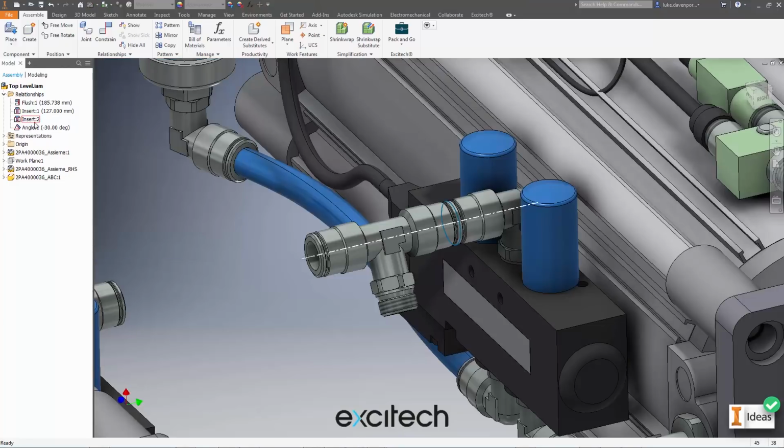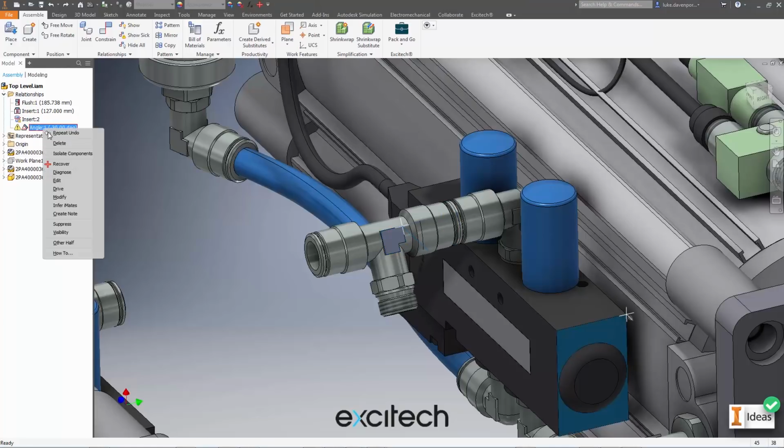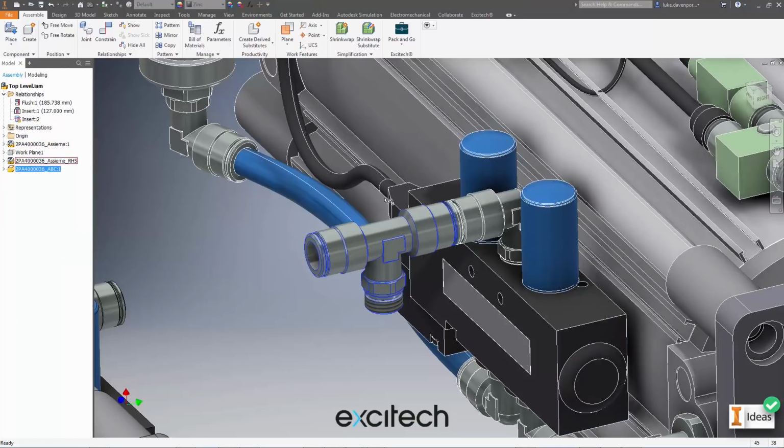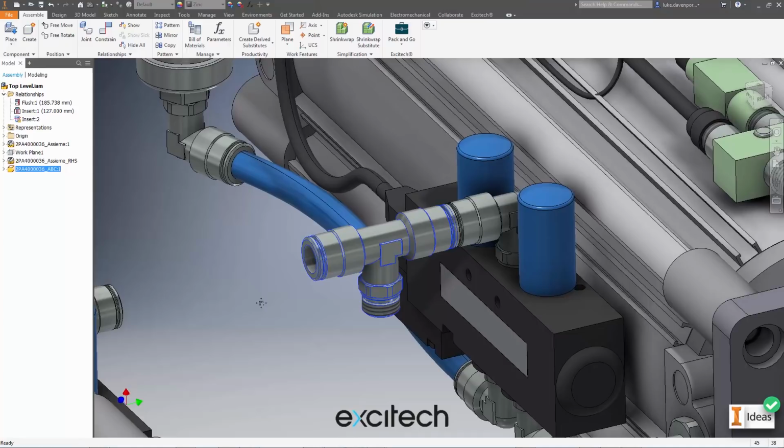We've got no error now. Or we can keep the insert locked if I hit undo, and we can delete the angle constraint, and the insert will then determine the twist of this component. So this gives us an idea of what this lock insert constraint is designed for.